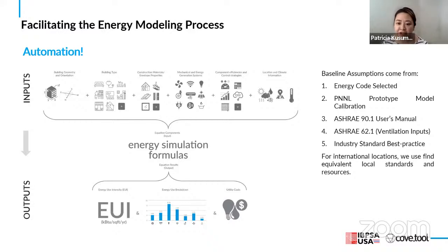We layer that with additional data from MEP disciplines and other energy conservation measures from engineers and consultants. With all of this information together in Cove tool, we can generate a building energy model fairly swiftly to use for performance simulation and analysis. Then we integrate some of the baseline assumptions based on the energy code selection that is pre-built into Cove tool, other calibration and energy standards such as ASHRAE, as well as industry standard best practices to run the energy performance